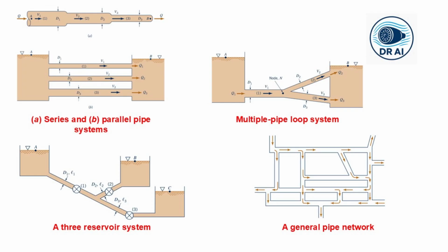So this is a powerful constraint. It means that even though the pipes may have different diameters, lengths, or roughnesses, the energy dissipated per unit weight of the fluid traveling through any branch is identical. Solving parallel pipe problems often involves expressing the head loss in each branch, as we have already seen earlier, HL equals f L over D times V squared over 2g, and then using the fact that these head losses are equal to relate the velocities in each pipe. You then combine this with the total flow rate equation to solve for the individual flows.